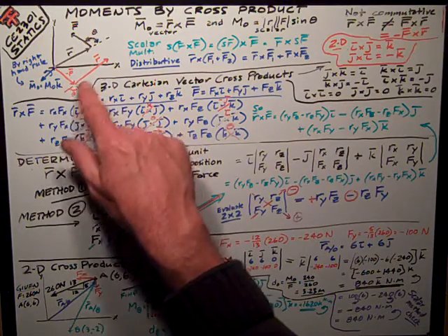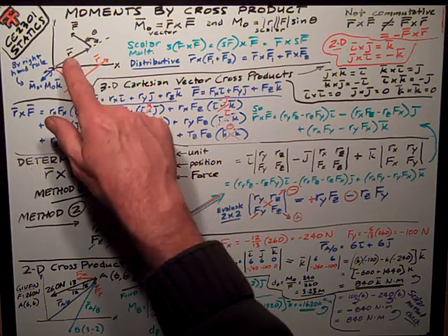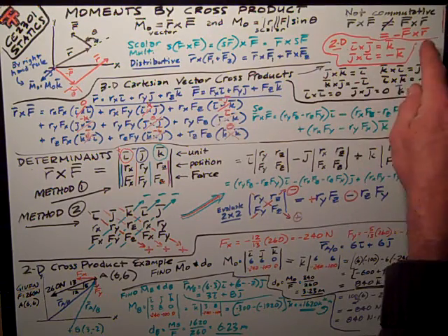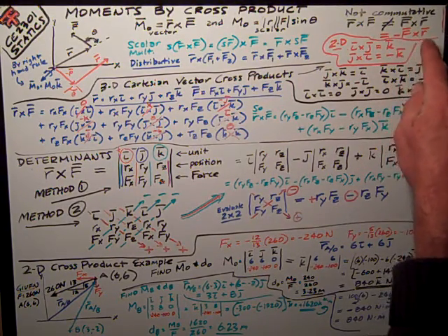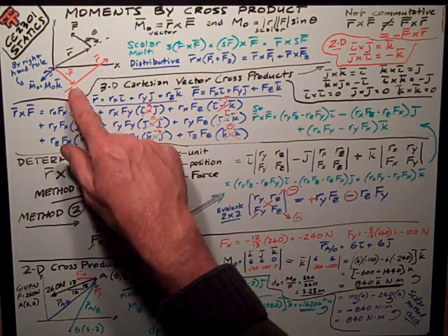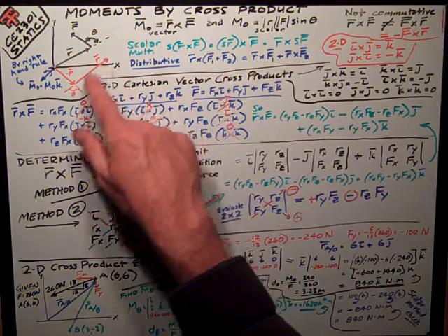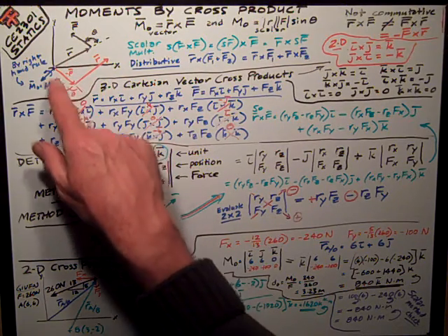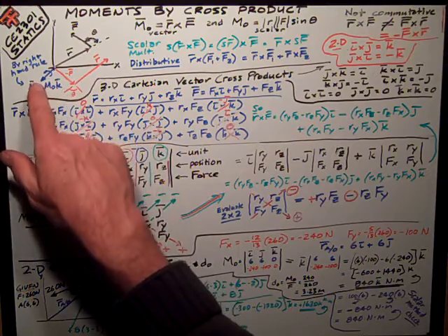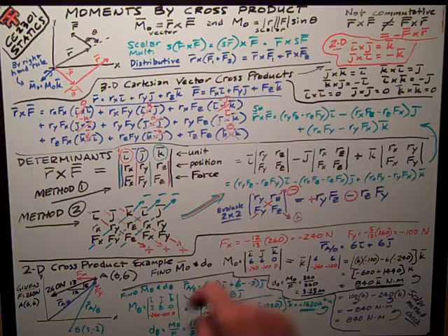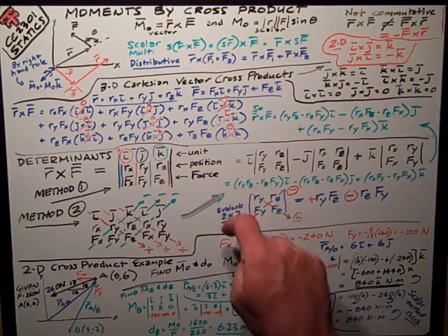And then at its tip I move the vector R, because it's the second one in this equation, negative F cross R, so its tail is at the tip of F and it goes off in the direction that it was over here. So that produces the same moment about point O, negative F cross R. We'll look at that again in a second.